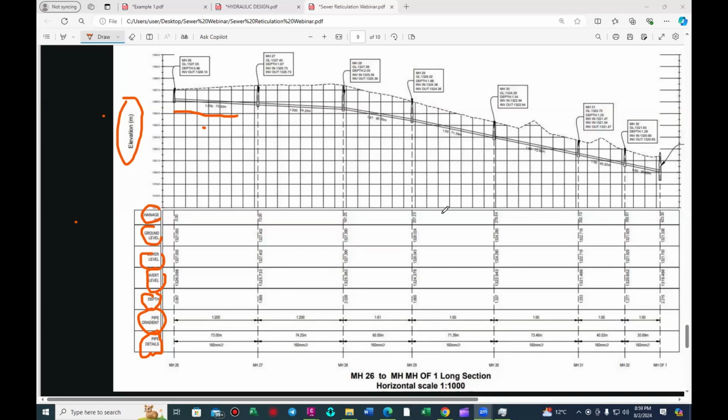So you'll be looking and say, okay, fine, does this slope make sense to me? Because you don't want to lay a sewer that has got depths up to 10 meters. So you see, okay, this slope gives me depths from 0.8 to like 1.2. Okay, let me try and use this slope. Then you assume a minimum diameter of 160 millimeters. Then you plug into Colebrook to see if that pipe can achieve the cleansing velocity, right?